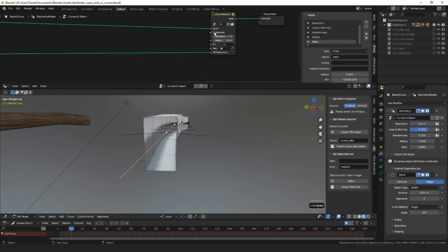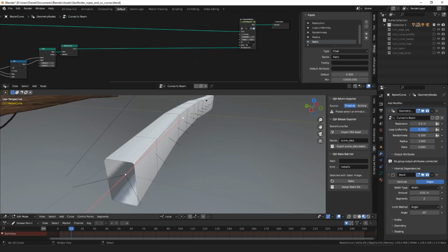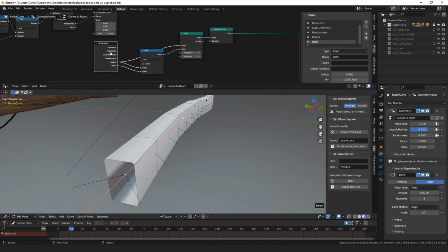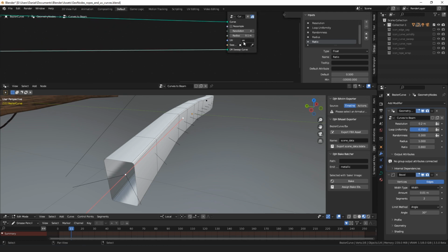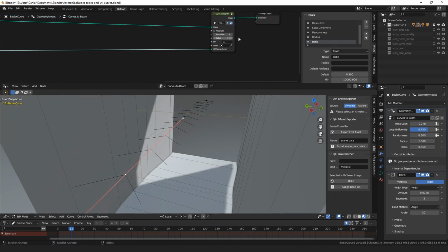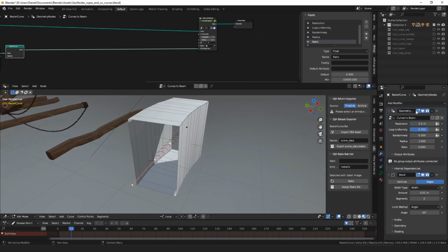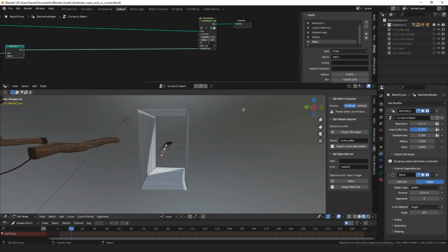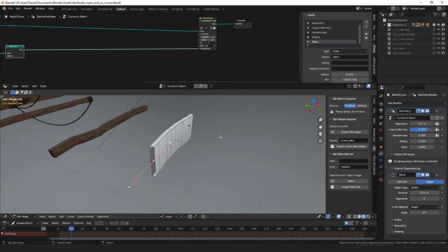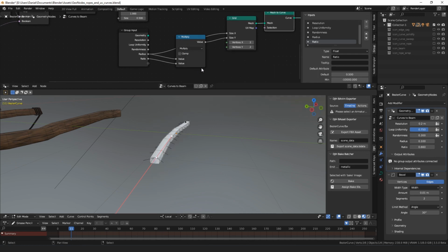So we put this in, we want resample off. That means the resolution shouldn't do anything. That fixed. Back to our radius and ratio. So now one thing is currently the radius is 1/10 because we also have a radius on the sweep curve. So let's make the radius here 1. And that way the value we pick for the radius in our curves to beam node reflects real world sizes. So we can see it's 1 meter tall. Let's make that 0.1 again. And then this should be multiply, not add.